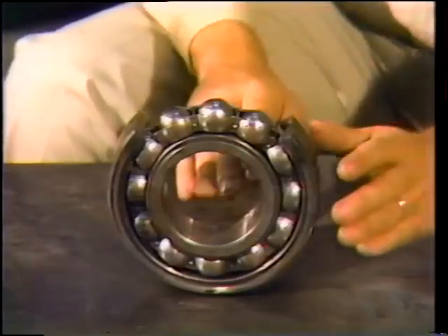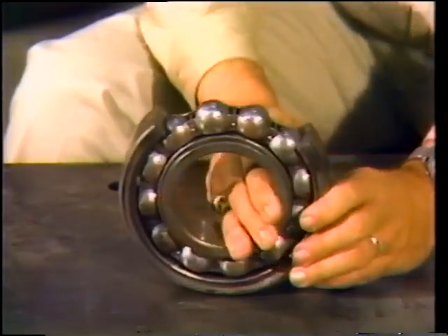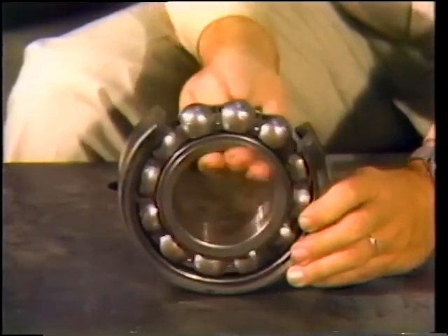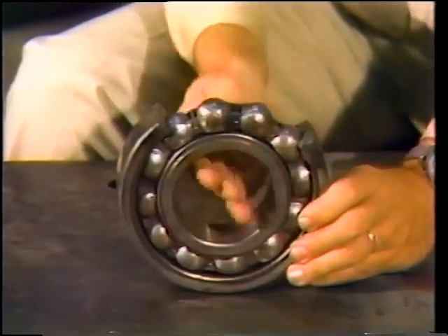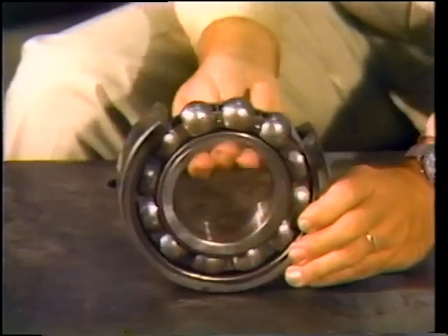The amount of friction produced in an anti-friction bearing is reduced by the rolling action of the bearing's balls or rollers. Since very little sliding takes place, not as much lubricant is needed to reduce friction. The other reason is that too much oil in an anti-friction bearing could make it overheat. If an anti-friction bearing were completely filled with oil, the balls or rollers would have to push the oil aside as they turned within the bearing, and this creates more friction than occurs when you use less oil.